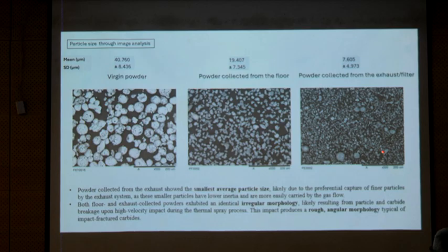In some other cases, not from this one, we have asked for similar material from somewhere else, because this was HVOF spray. My ambition is to look at what happens with HVAF waste and plasma spray waste. I am looking at all of those. From some other supplier, you see chunks of alumina. This is incidentally tungsten carbide cobalt. Very expensive powder, extremely expensive powder. So if I can get anything sensible out of this, I am in good shape.